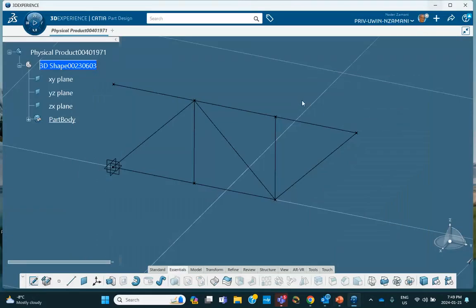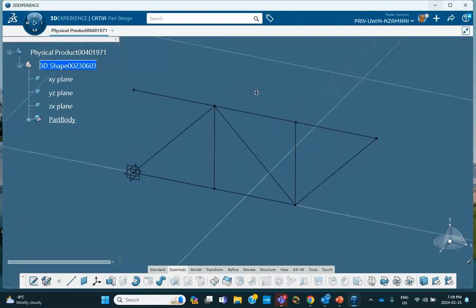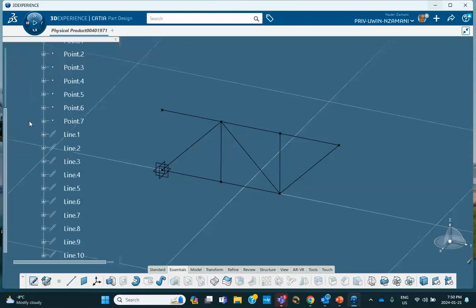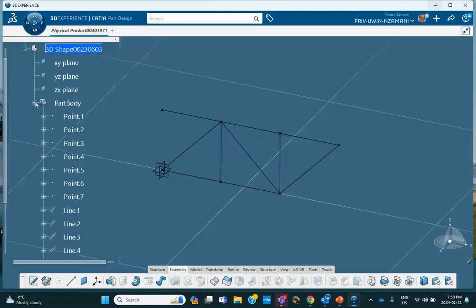And now there are different ways of doing this. I can, for example, join these lines and mesh the whole thing, or mesh them one by one. That's entirely up to you. So to make my job harder, I'm not going to join them. I'm going to mesh them one by one. You see why in a second. All right, so this is the stuff. And now I'm going to create a material.